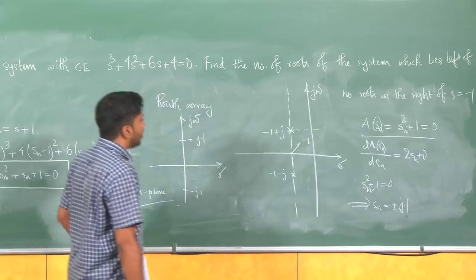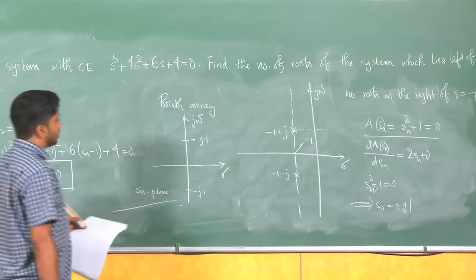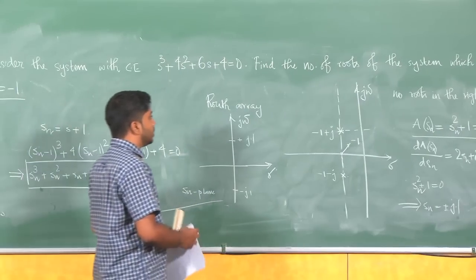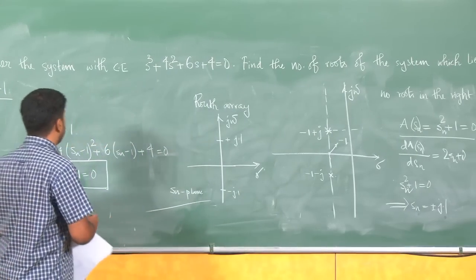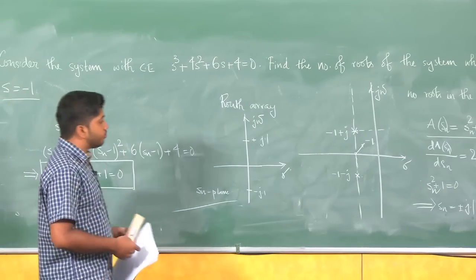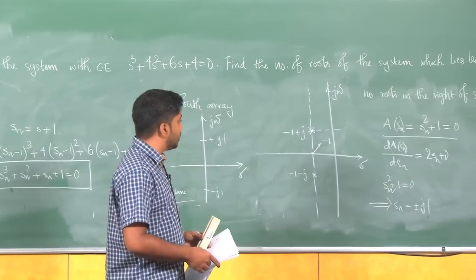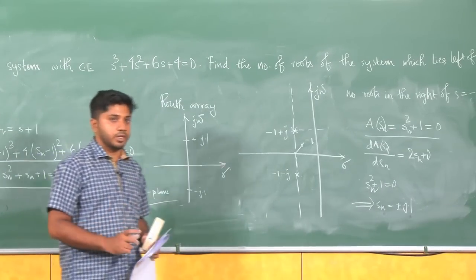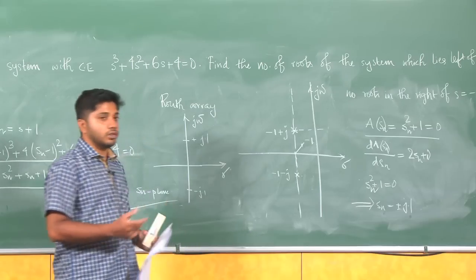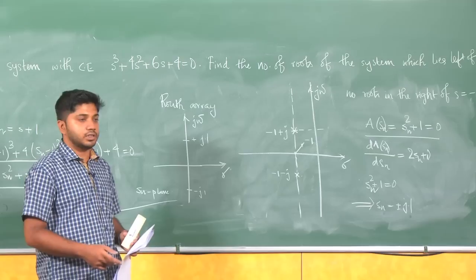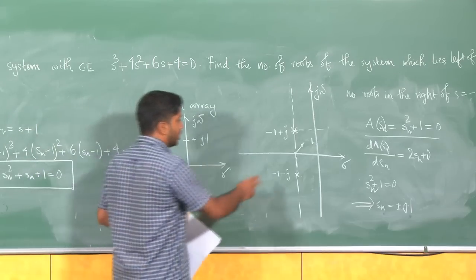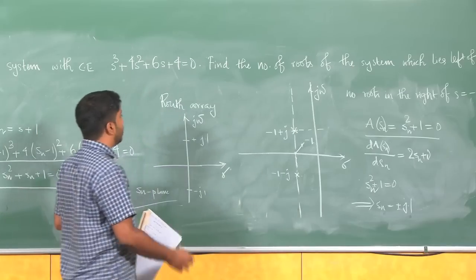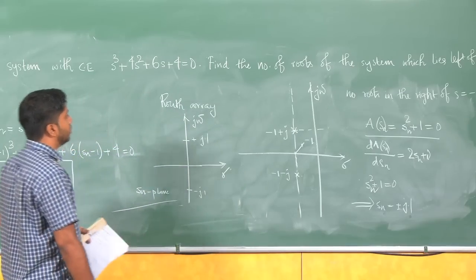This kind of axis shift is very useful in systems where there are a number of complex roots, so more than one complex pair of roots. If we are going to determine the relative stability of the system based on how the roots affect the damping of the system, this axis shift method using the Routh Hurwitz criteria will be helpful.